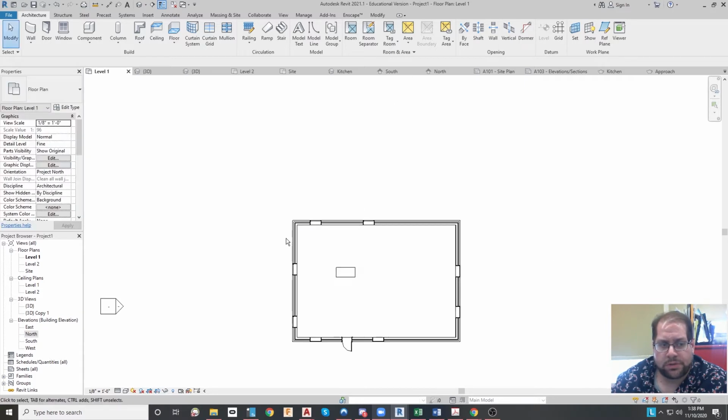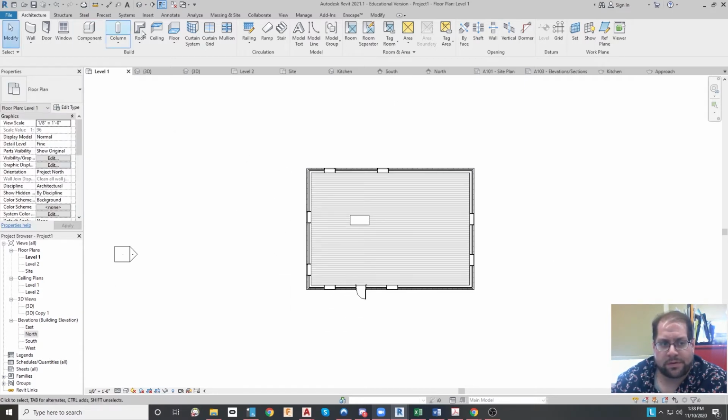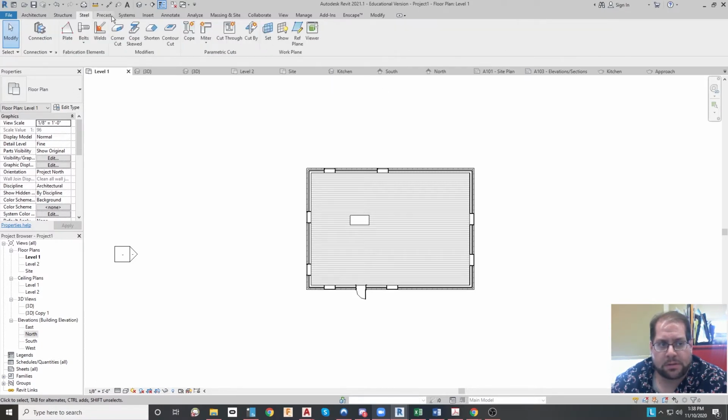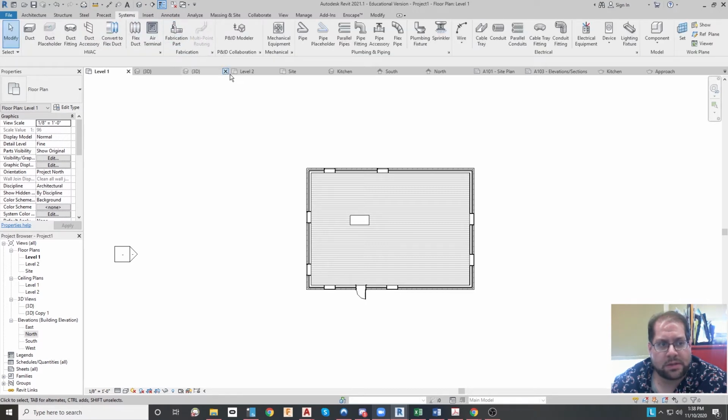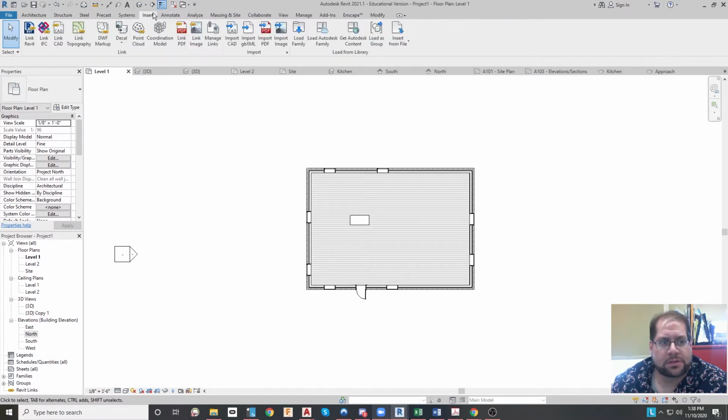Most of the controls that you're going to end up using inside Revit are found very easily on the ribbon. So this ribbon has controls grouped by style or type. Like these are architectural commands, structural commands, steel-based construction commands, anything that's precast as far as parts and splitting things, and a few other things. The systems tab has things you might find like ductwork and plumbing and electrical. Insert is for a whole bunch of things that you'd be able to import and insert into the program.